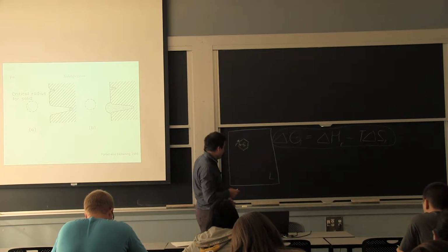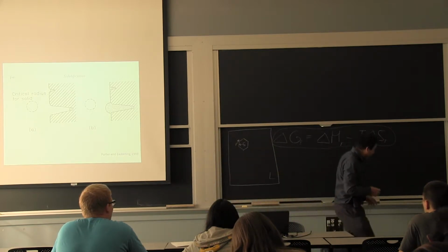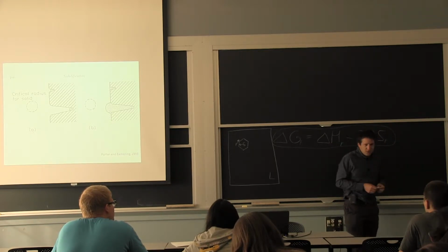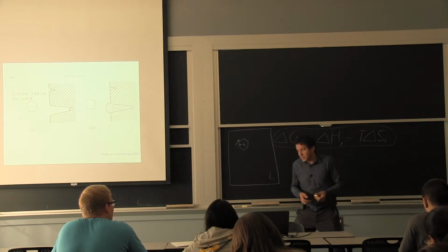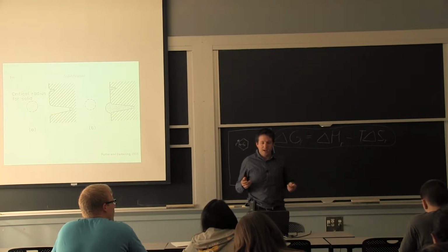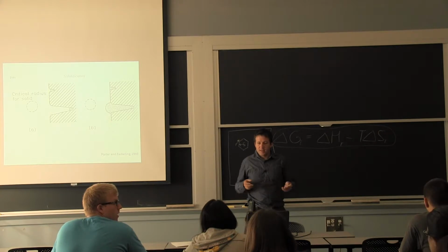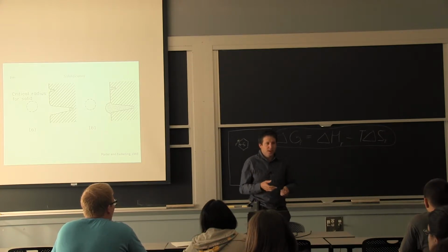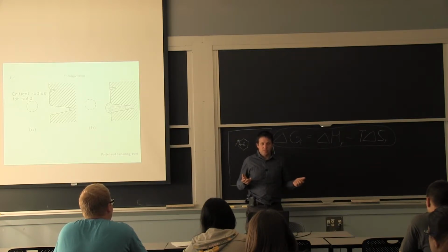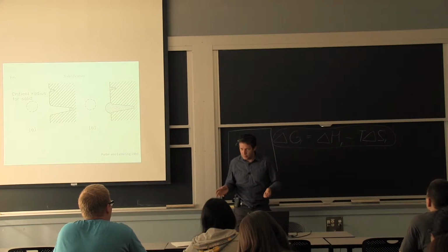And that may be the right time to introduce the example of a turbine blade. What you do with a turbine blade, if you want to use it at very high temperature, is it needs to be metallic. One reason for having it metallic is it will be able to withstand higher temperature and still have a good fracture toughness. So you gain the fracture toughness by making it a metal as opposed to an intermetallic or a ceramic composite. But you'll have creep at high temperatures. So the way to design out creep is to make it a single crystal. It doesn't eliminate creep, but it reduces it.